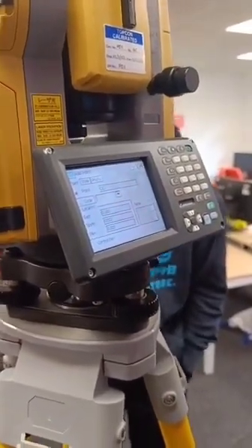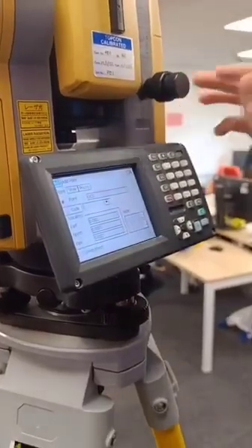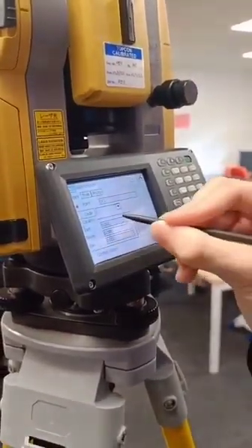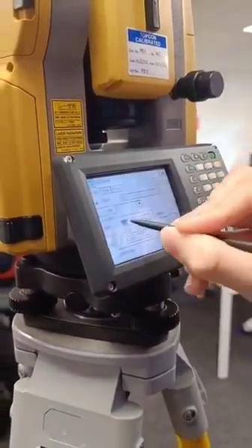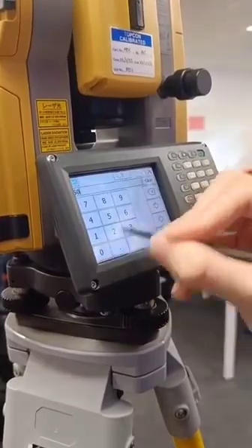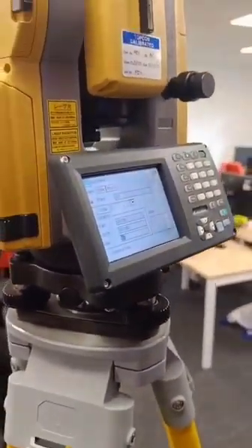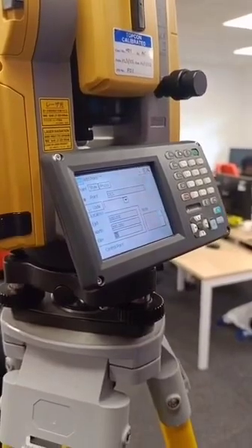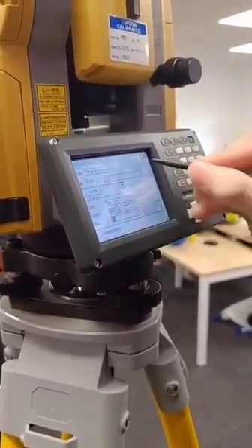So it's like when you open it in CAD or Revit, whatever, it tells it, okay, this is where it is. For the machines, they've got a manual, and the default they tell you is to use 100 easting, 200 northing, and 50 elevation. So we're turning it 100 meters east, 200 north, 50 up, so that when you take your measurement points, they don't go below 0 on your thing, because it looks a bit weird. And then I just hit tick.